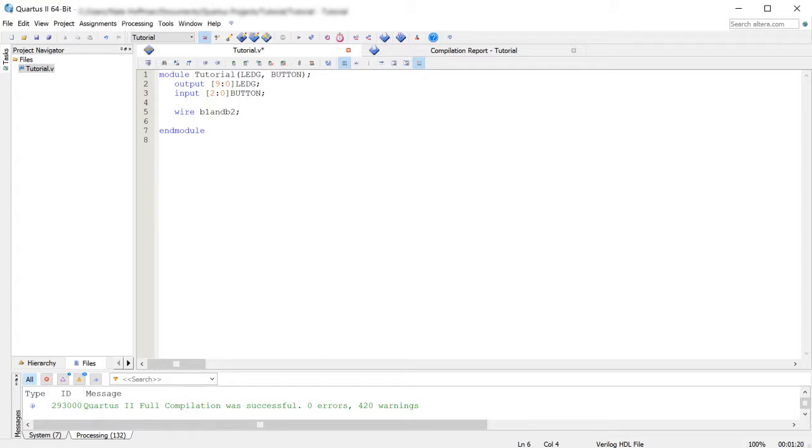So what I'm going to do is I'm going to do and you're going to see that highlights there, or colorizes it blue. And then I'm going to make it the first variable, which is the output of the AND gate, B1 and B2. Then put in a comma and a space. So from here, you can put in as many other variables as you want, and it will AND everything together and make it go to this one output, which we have as a wire. So for this, I'm going to do B1 and B2 as the AND.